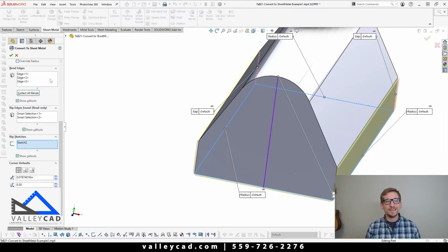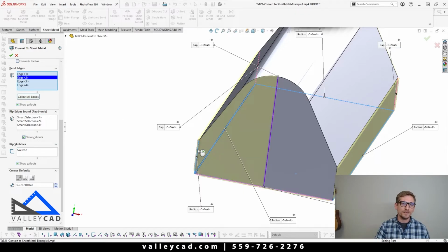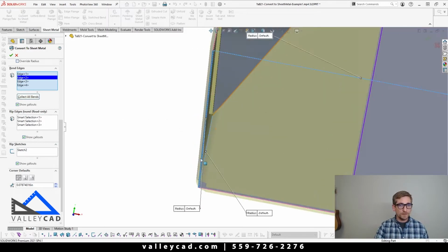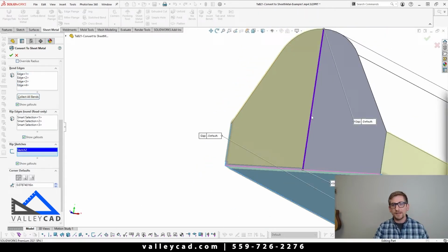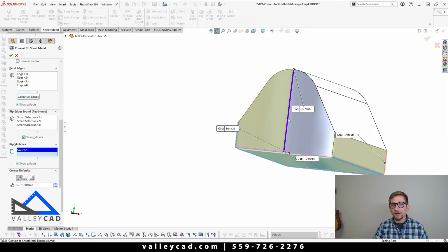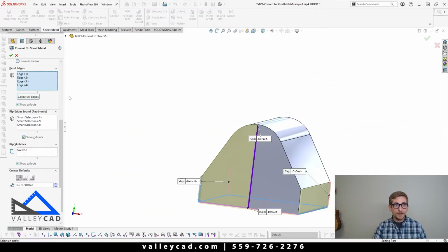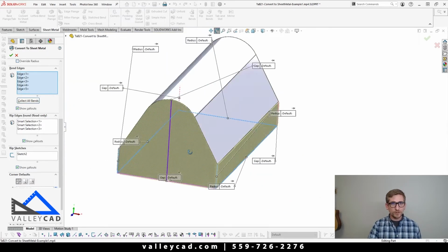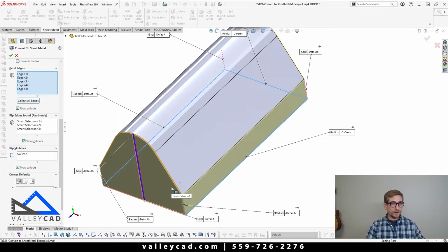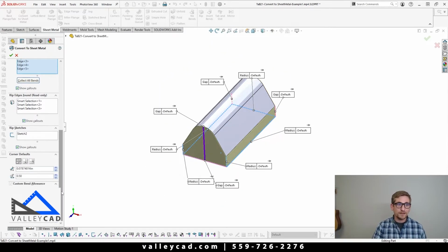Not yet. So I'm going to come back up to bend edges. Watch what happens when I click on this edge. SOLIDWORKS will come through and it'll bend from here. That's great. It's ripping from down there. But since I used rip sketches, it added a rip here, so it's actually stopping it early. Cool. Then from here, I could specify this edge over here, and SOLIDWORKS will come through and form it around that little short leg there. Then from there, I can simply click on OK.